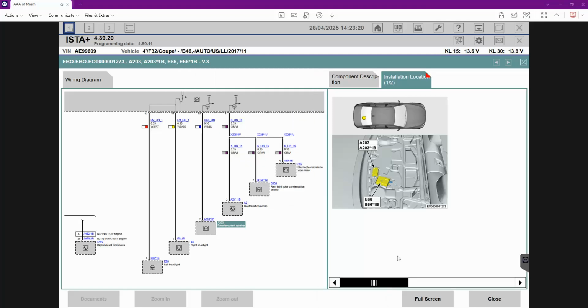Alright, BMW enthusiasts, you troubleshoot and find it. Then you run a calculated test plan and click on the ABL concern about whatever the fault code is saying about a particular function. Then you pull up the wire diagram in the test plan, and you can click on the different hyperlinks, the blue writing on the wire diagram, and it will bring you directly to the spot in the car where the device or component is installed.